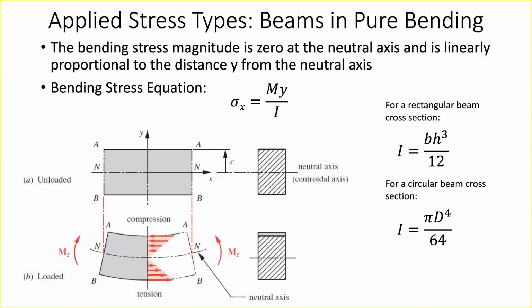So if I take my phone and bend it like this, you basically get two different types of stress. On the top surface, where I'm bending it together like this, you get a compressive stress, whereas on the bottom, you get a tensile stress. Compressive means it's pushing together, and tensile means it's pulling apart at the bottom. You can see that depicted in this image. The unique thing is that there's something called the neutral axis. For any part that you bend, regardless of the geometry, there's some line on it where there's zero stress. That makes sense, right? You're transitioning from a tensile stress on the bottom to a compressive stress on the top, and at some point, you have to pass zero to do that.